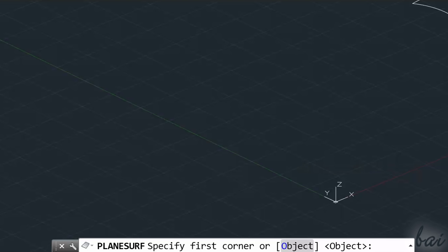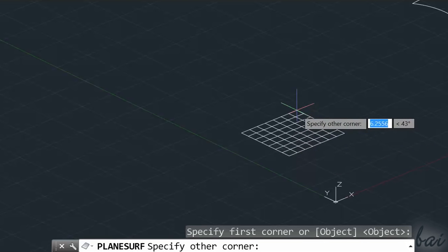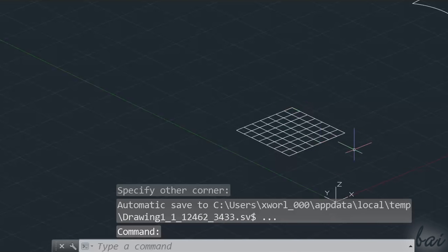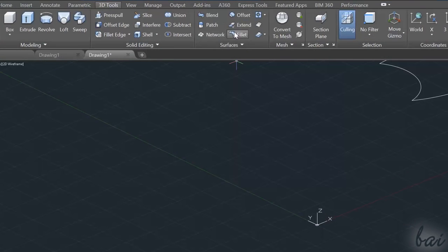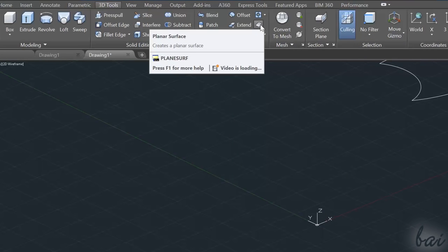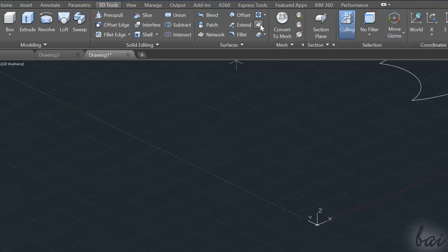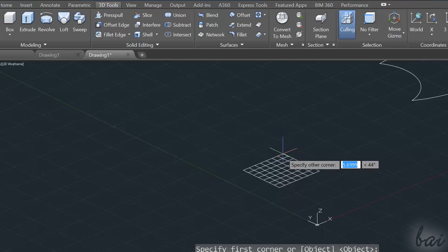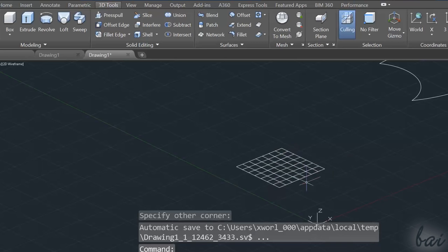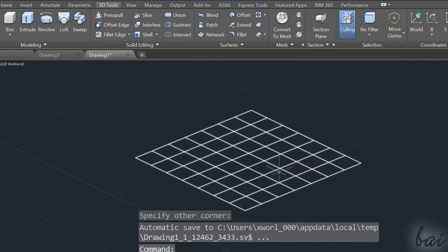The simplest surfaces you can create are the planar ones, such as surfaces that lay on a single plane. You can draw these by using the Planar Surface tool. You can use this tool in two main ways. If you enable the tool and click and drag on your workspace, you will drop a rectangular planar surface just as seen with the Rectangle tool.